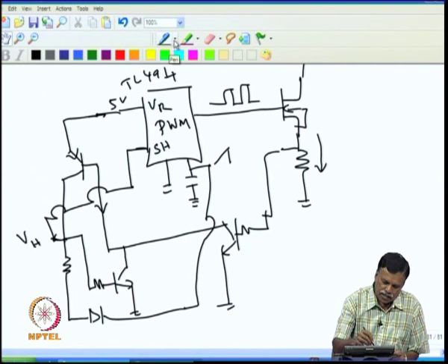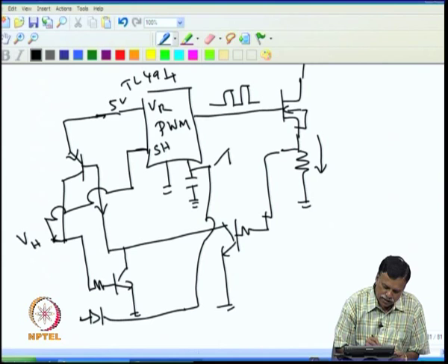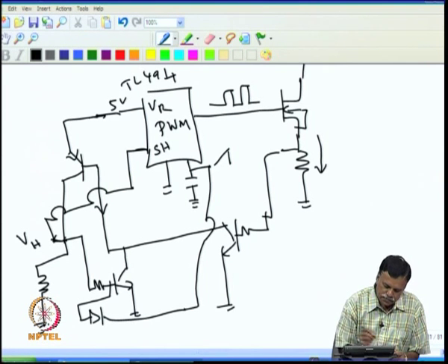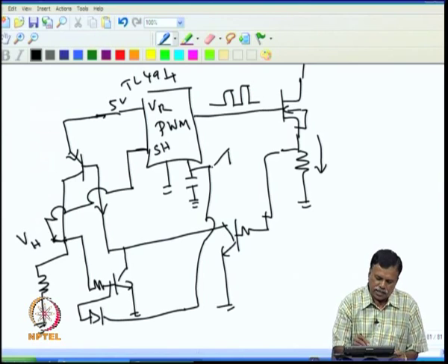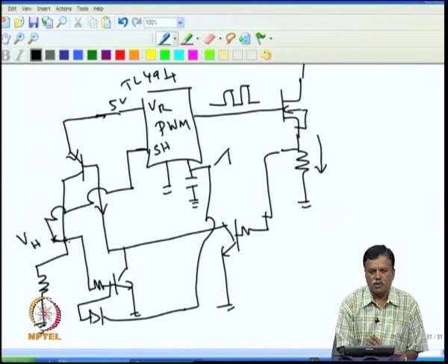For example, I can connect this diode here. So, I put this. Now, once the voltage at this point drops to 0, this voltage will be dropped to 0 and this transistor will go out of conduction, and this voltage also will disappear.